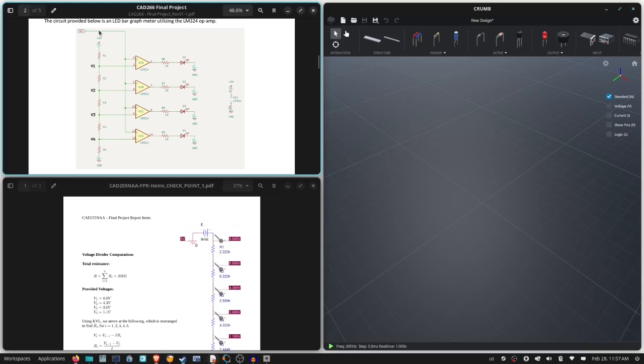and we are basically dividing 9 volts using the voltage division principle into four reference voltages, and then we are feeding in another voltage, which will be compared to our reference voltage at each division level. For example, let's say all of these resistors are equal, and that means it's going to drop the same amount over each resistor from 9 volts to ground.